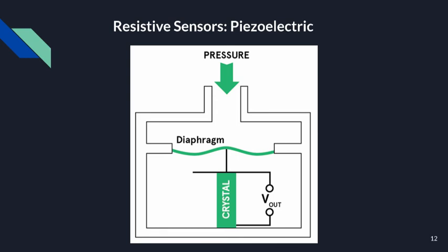These transducers are typically made from piezoelectric materials. These materials have an asymmetrical lattice of molecules that distorts when a mechanical force is applied to it. This distortion causes a reorientation of electric charges within the material, resulting in a relative displacement of positive and negative charges. The charge displacement induces surface charges on the material of opposite polarity between the two sides. By implanting electrodes into the surface of the material, these surface charges can be measured as an output voltage.